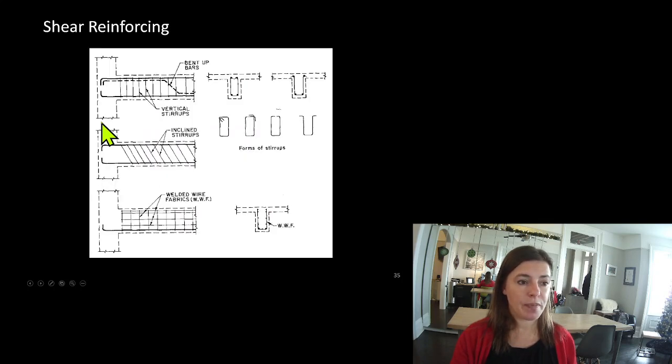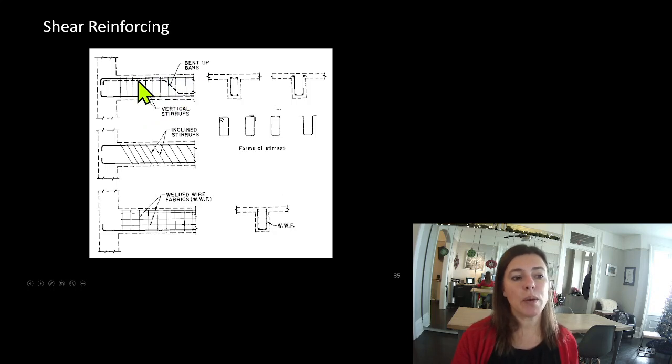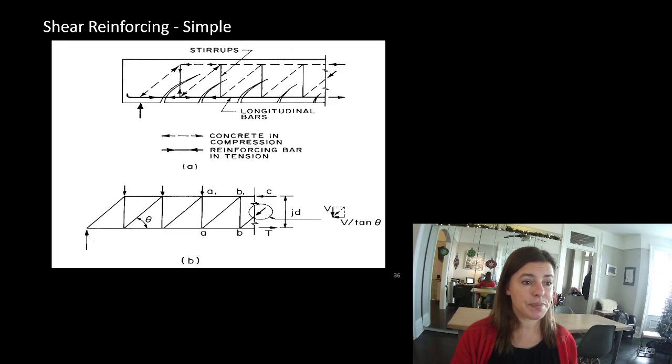along the beam. So here you can see what it looks like where we've got our ties along the length of our beam. So often we would say that these are 10s at 300. So every 12 inches we have a tie that looks like this. So there's a lot of steel hidden inside our concrete beams.